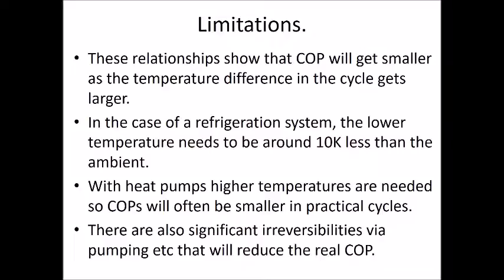So let's take an example, maybe of really cold outside, perhaps sub-zero down in the ground or the water, the air that I'm pumping from. It's not necessarily the temperature of the ambient environment I'm trying to maintain, say 20. It's not that. It's the temperature of the refrigerant inside the radiators. Now, radiators themselves, what temperature are they going to run at? They're going to be around about 40 degrees Celsius, perhaps. I've got a huge delta T in that case.